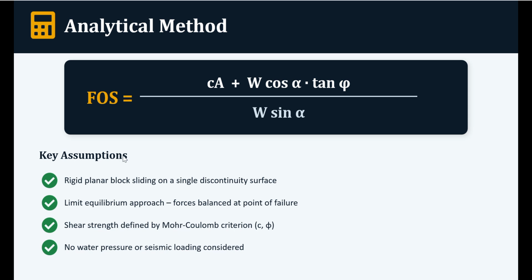And these are the key assumptions. A rigid planar block sliding on a single discontinuity surface, only a single discontinuity, and the limiting equilibrium approach, which is forces balance at the point of failure. The Mohr-Coulomb criterion is used for the strength envelope. There is no water pressure, no seismic loading, and no dynamic analysis. Simply these are the key assumptions here.